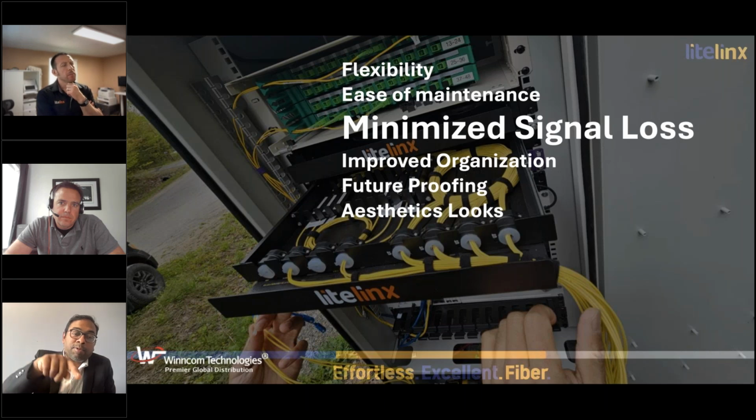The second card goes to the second port, third card goes to the third port, fourth goes to the fourth port. And believe me, 4 ports are more than sufficient in most of the rural deployments we will do. They can service about 5,000 customers from those 4 ports on that splitter box. And on the right-hand side, the other 4 ports are the output ports.